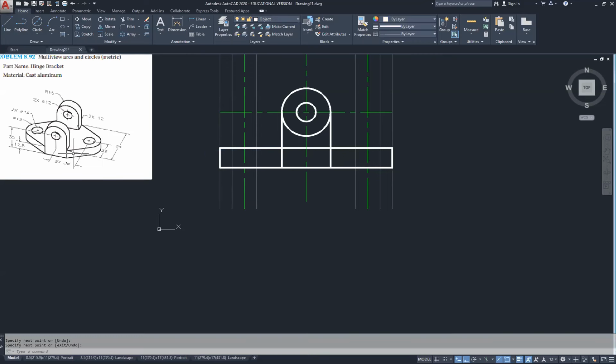Now, you'll notice a difference between the front of this, how smooth and flat that is, versus that I have a line here. I'm actually going to trim that line out using the trim command to cut that away. But there is a line behind that because this has a backside. You can see this backside from this one, which from this view would be more of a front, but it's behind something else. It has a line back here as well. So those two lines indicate that there should be a line here.